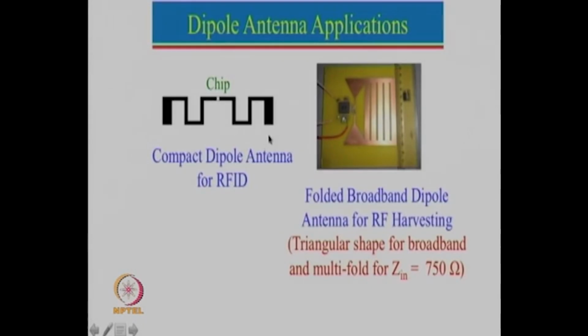So in India, the band which has been given is around 866 megahertz, whereas in other countries the band is actually between 915 to 935 megahertz. But there are RFIDs also available in the frequency range of 13.56 megahertz or 125 kilohertz and so on. But here is an RFID example which is designed for, let us say, around 866 megahertz or 920 megahertz.